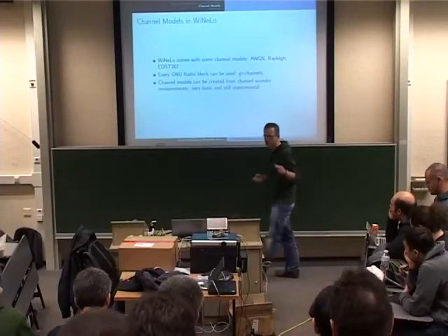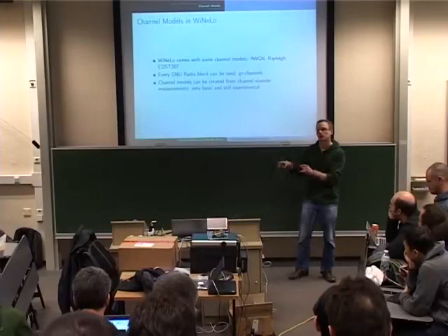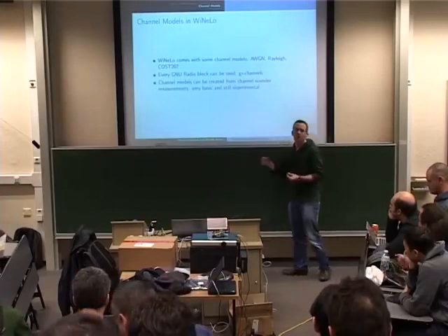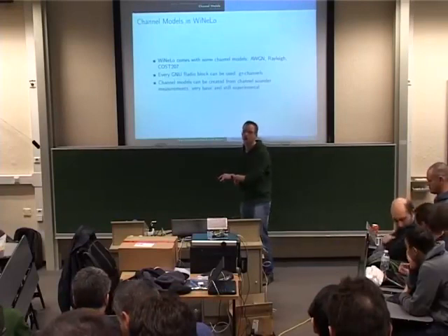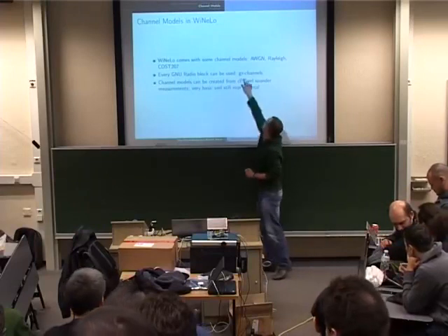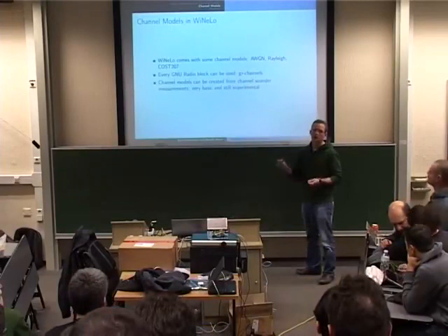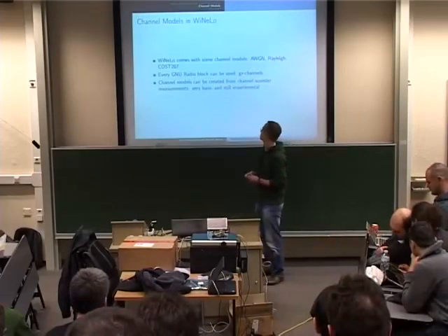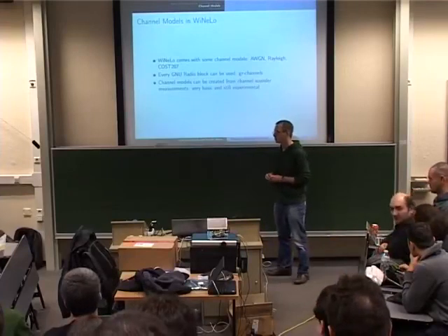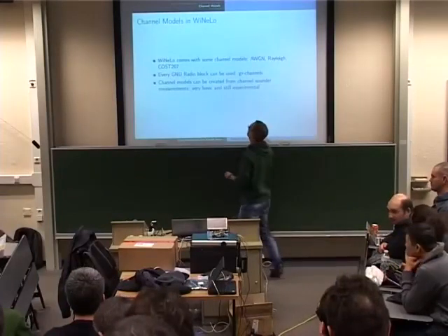For the design of wireless networks in the loop, the server is basically running a GNU Radio flow graph which simulates the channel, so you can plug in pretty much any GNU Radio block as a channel model. And as of 3.7, there's a project called gr-channels from Tim O'Shea, and he implemented a couple of channel models which you can also use. So Tim's channels are now part of GNU Radio 3.7? Yeah, I think I mentioned it.